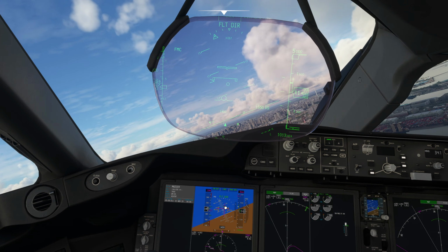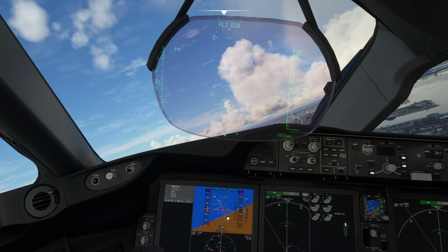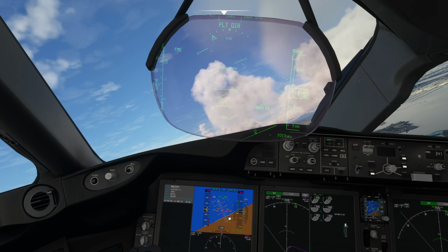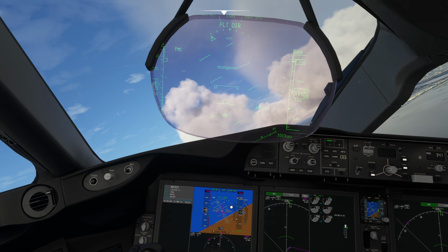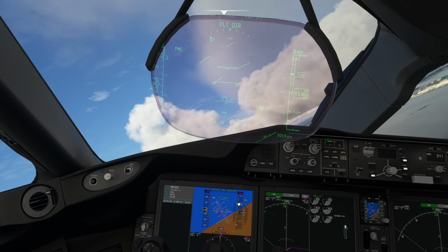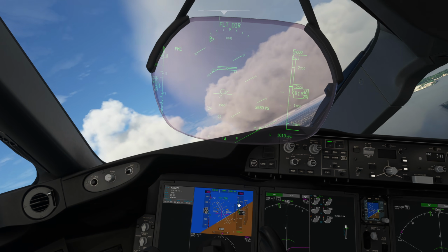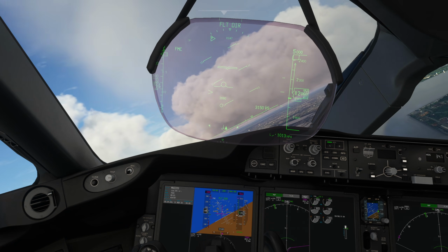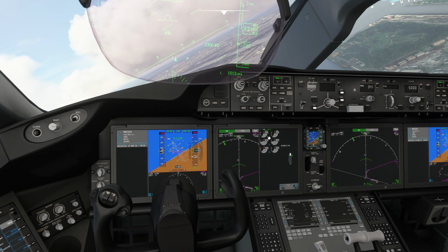If you're struggling with this, you can use the PFD with a traditional flight director. Otherwise it's quite a difference. We're well through 400 feet now, so you can see we've gone into LNAV and VNAV speed, and we've gone through 1500, so it wants us to accelerate, so we can lower the nose down, and the thrust has gone to climb 2 thrust over here.